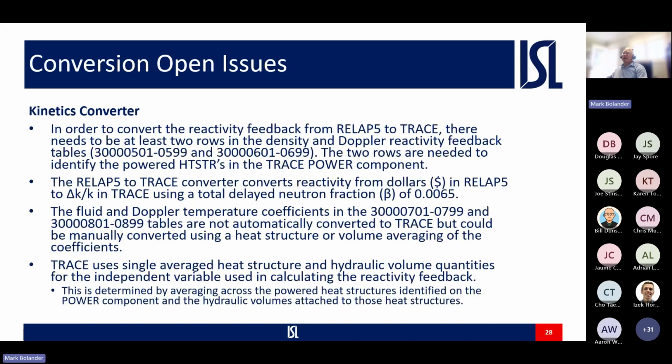The kinetics converter: in order to convert the reactivity feedback from RELAP5 to TRACE, there needs to be at least 2 rows in the density and Doppler reactivity feedback tables in your RELAP5 model.